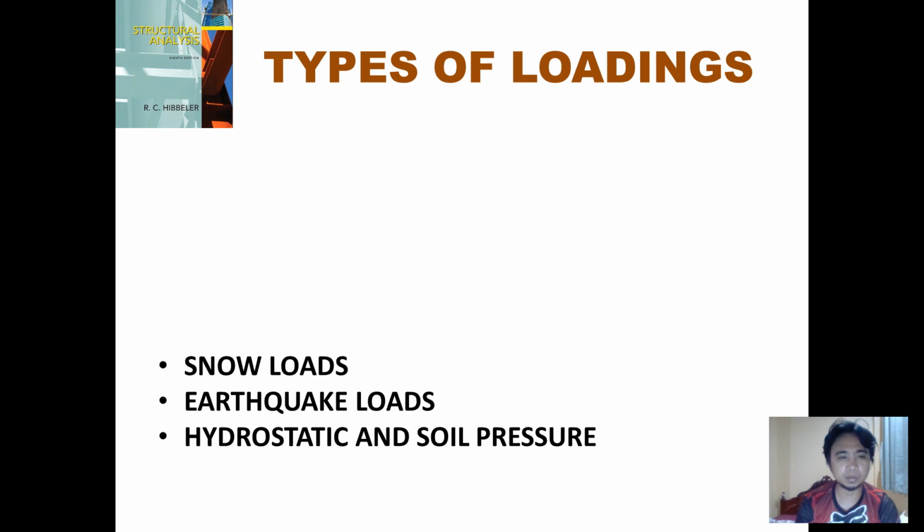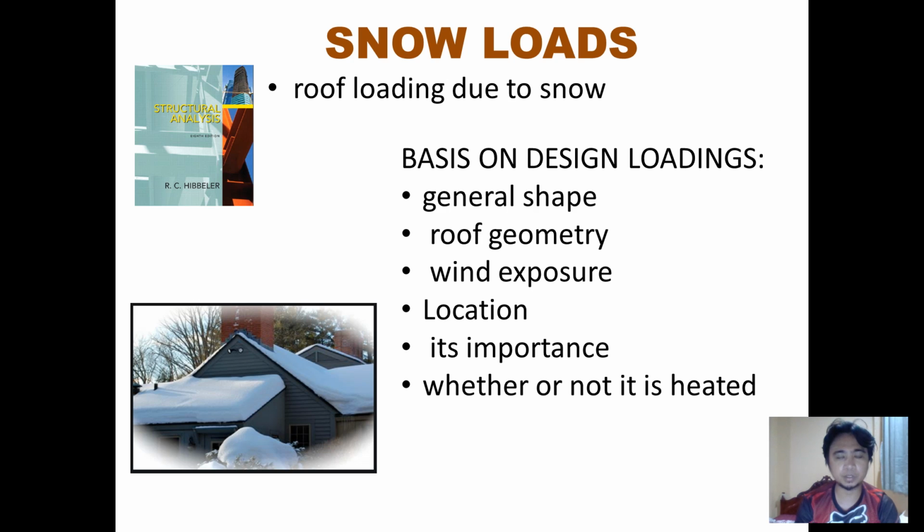Basically, snow loads are not so much a concern in our country, but at least we should have some knowledge of them. Snow load is a roof loading due to snow, as we perceive that snow will be accumulated on the roofing. So basically, our design loading is associated with the general shape, roof geometry, the wind exposure location, its importance, and whether or not it is heated.